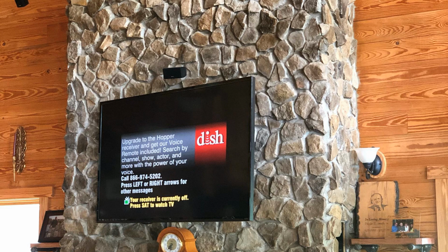Those areas you don't want to let mold. You don't want that to get out of control. You don't want that to be something that's not your problem that you have to deal with later. One excellent way of figuring out what's going on with this wall may be to come to this light fixture on the right side of the photo there and take that light fixture down, and maybe you'd have to take the box in there loose, but to be able to inspect the hole in that wood wall so you see what you got. You've got to know what you're drying so you can know if you can dry it or not.